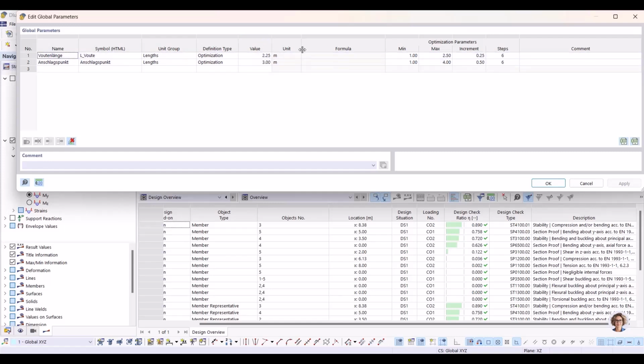If your parameters would reach all the max value or reach a minimum value, this could mean that you have to increase your max or min values, because your optimized system could lie outside your defined max or min parameters.